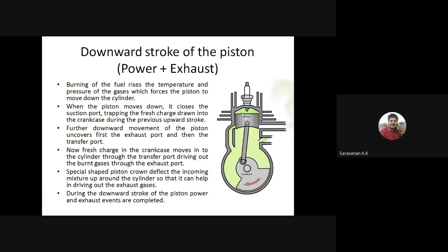In this type of two-stroke engine, it is not possible to put lubricating oil in the crankcase. So we add the lubricating oil through the carburetor, where the mist is mixed, so the air and fuel mixture gets the oil also. This is the type of system.